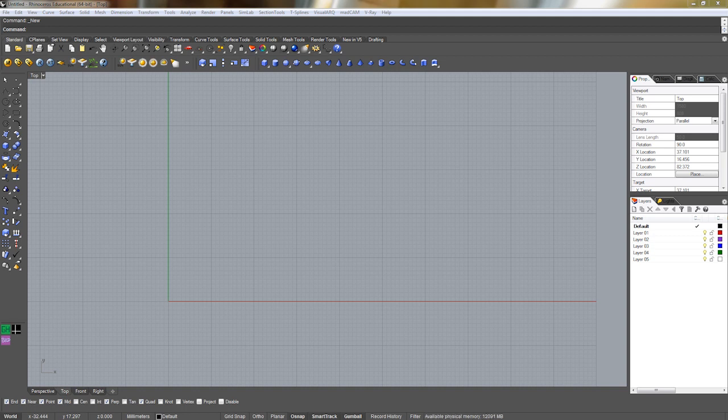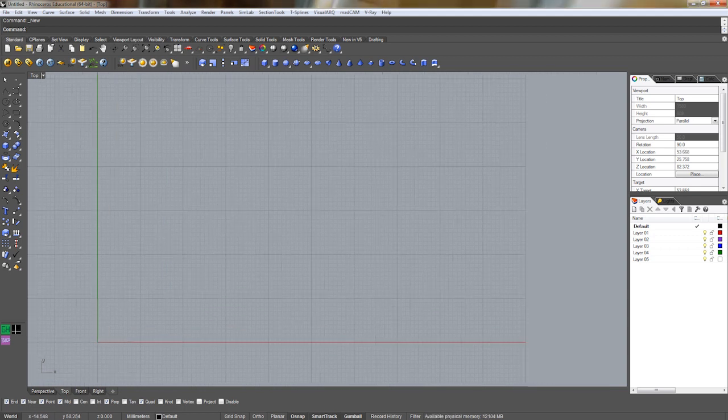And I'm going to show you how to set up the animation path in Rhino and render it with Vray. So let's start with the first modeling part. I'm going to do this very quick, so open a new file, millimeters small. Do the curves. We're gonna do a layer for all the curves.